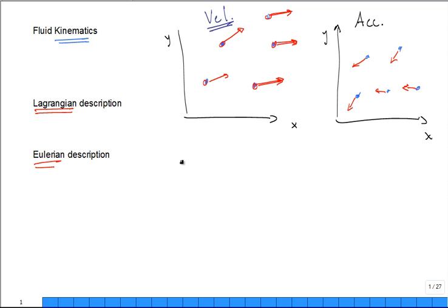The equations of motion, F equals ma, or the sum of the forces equal to the mass times acceleration, describe the motion of particles of fluid. The particles of fluid flow through the flow field. This applies for particles, but we like to plot things at points: points in a grid, points in a region, points in a field. But the point has different particles flowing through it, and F equals ma applies to the particles, not to the points.